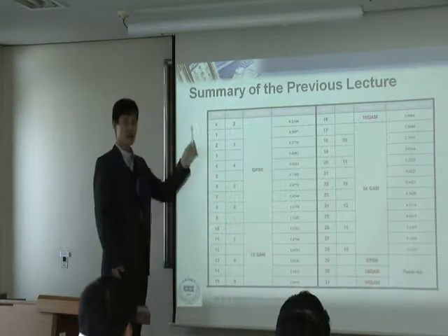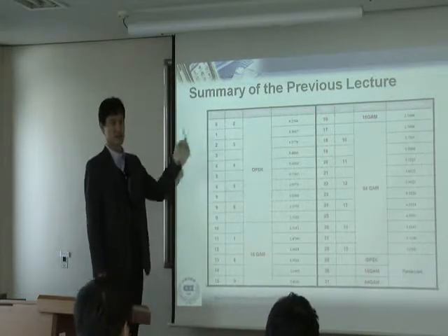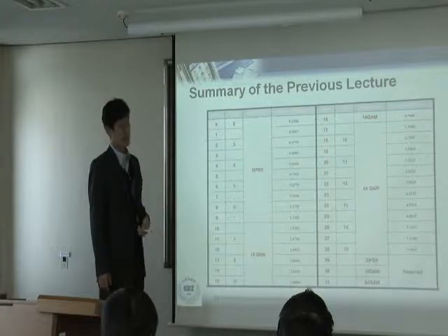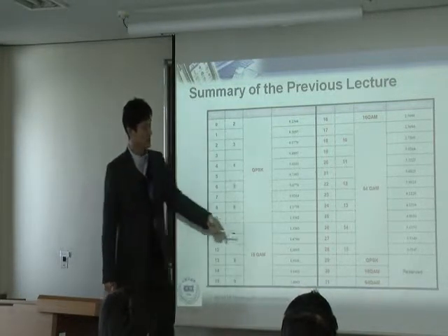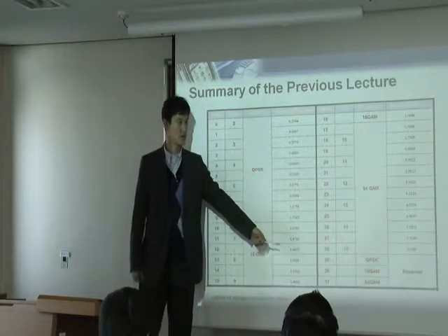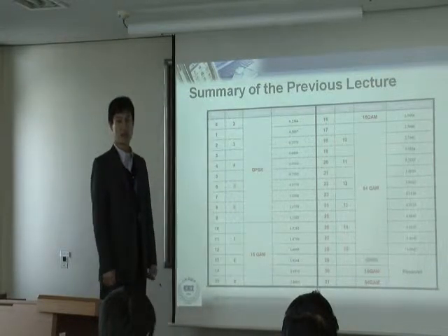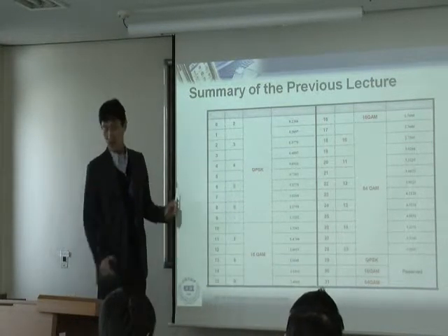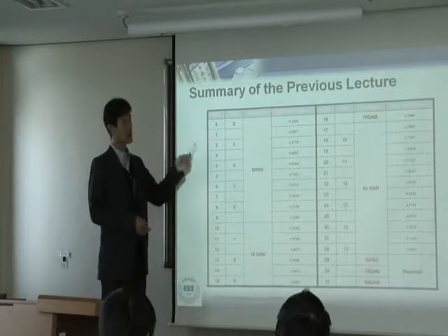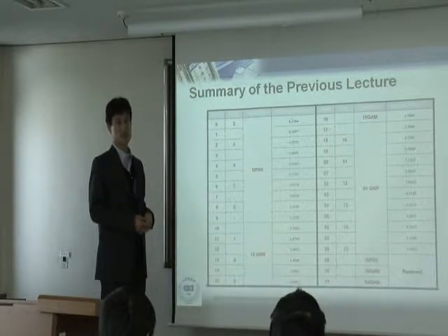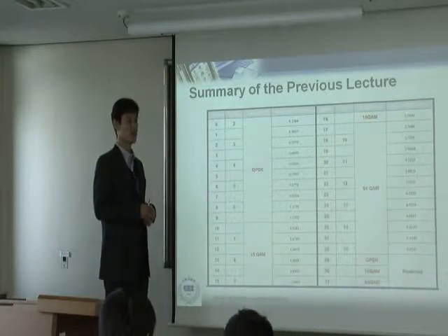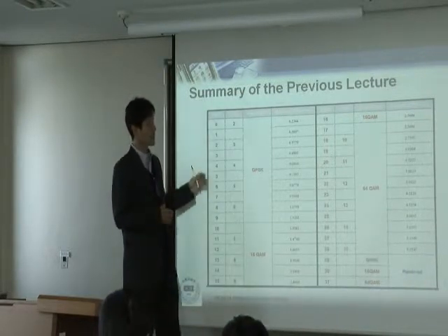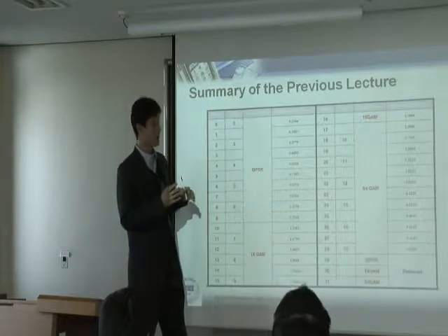Typically, the size of an MCS table like this is a power of 2. This is 32. And sometimes, in fact in the 802.11 wireless LAN case, the size of the MCS table is 64. It's always 2 to some power, and the reason is the receiver.